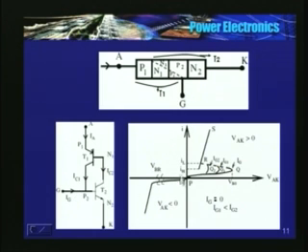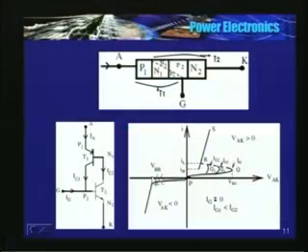And here are the SCR characteristics. I will explain to you now. In the reverse bias mode, characteristics are almost similar to that of a diode. VBR, reverse breakover voltage. So you should ensure that the applied voltage is less than VBR. Same thing, for the diode I called it VBD, here I am calling it VBR.